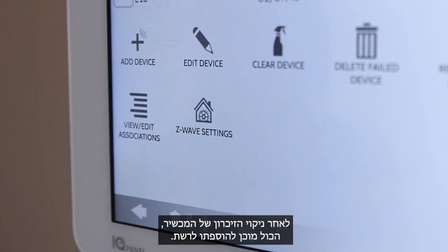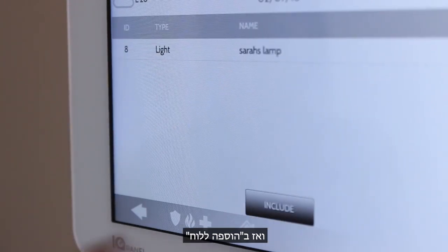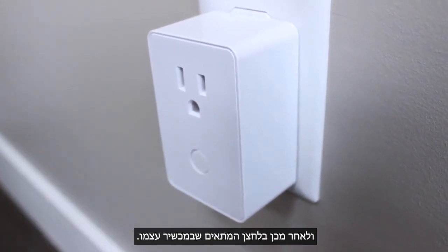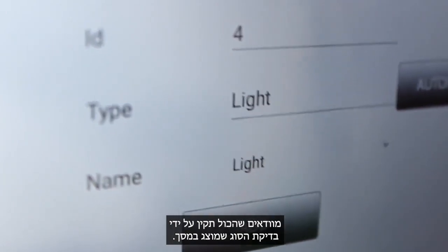With the device cleared, you're now ready to include the device in the network. Start by touching Add Device, and then touch Include on the panel, and then the corresponding button on the device itself. Once it's complete, verify that it's correct by checking the type shown on the screen.